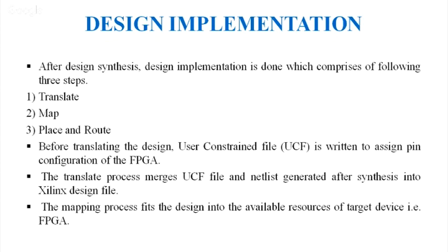The first step is translate. What does this step do? It merges your UCF file and the netlist, which is generated in the synthesis process, into a Xilinx design file. After that, the mapping process comes. The mapping process fits the design into the available resources. Available resources means our FPGA.